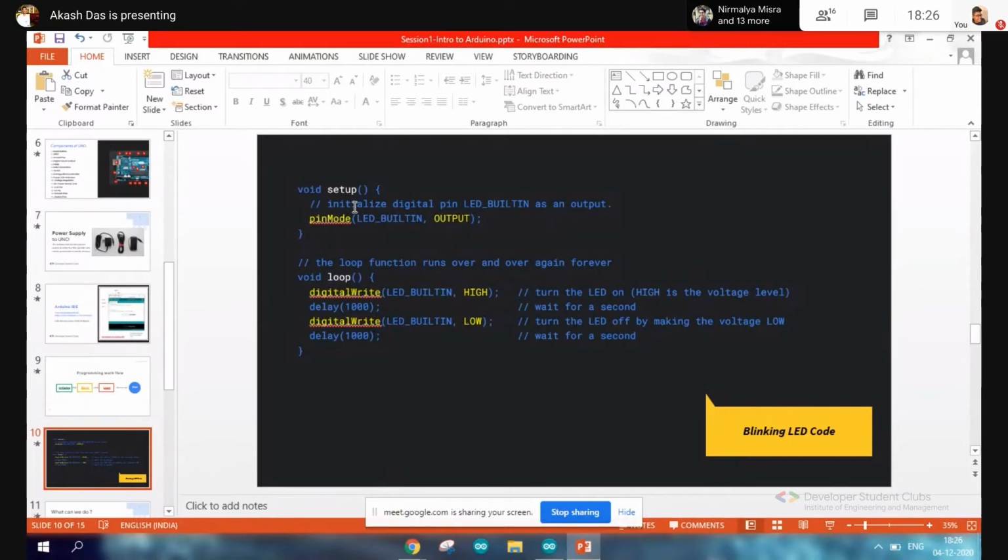When you're seeing a very large Arduino code, you first go into the void setup and see what is getting initialized and what is the initial condition of the peripherals. Then you go to the void loop and see what functions it is calling and what commands it is executing.